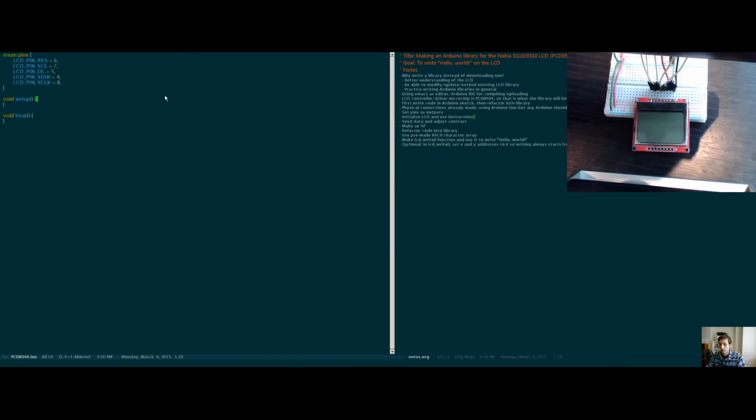But even before we get to that, we should realize that all of these pins that we're controlling with the Arduino Uno should be set to outputs, because we are the one giving information to them with the Arduino Uno, not the other way around.